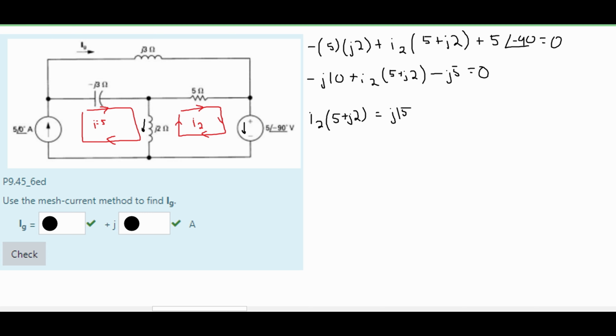I did make a mistake. I did get the current going against our I2 this way. However, I did not get the current going for our I of G. We know we have current going this way because the current flowing through our I of G will look something like this. So since our IG is flowing in the opposite direction, we can't set it equal to 0 just yet because we still have to plug in more. We will have a minus because again our IG is flowing in the opposite direction, and it's happening over the 5 ohm resistor. So we will have our 5, because this is the resistor it's over, times our IG, and now we can set this equal to 0.